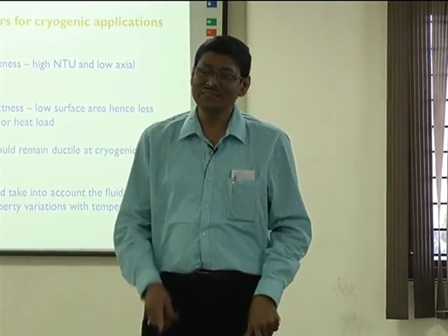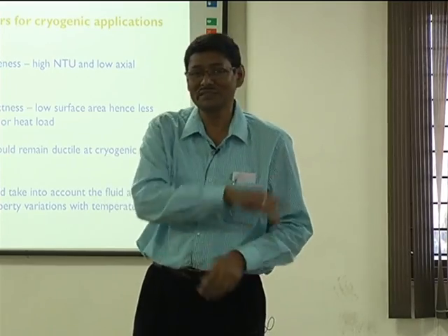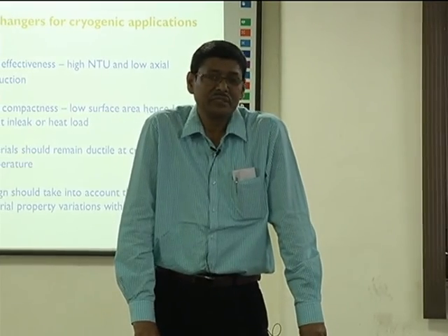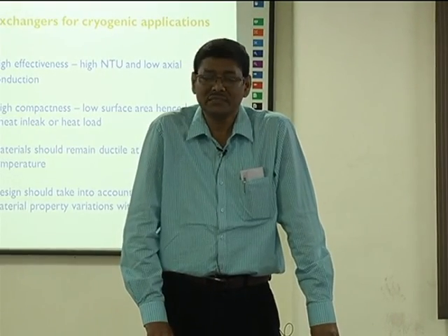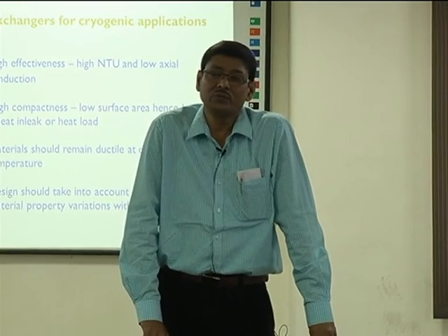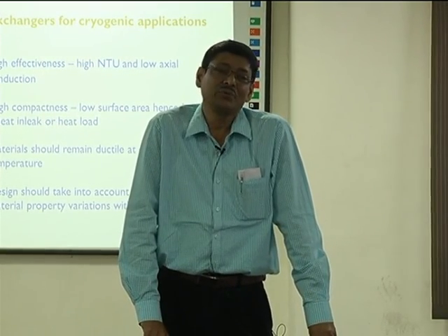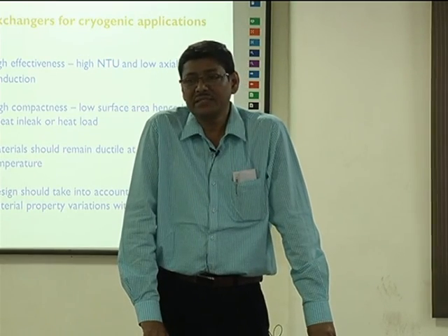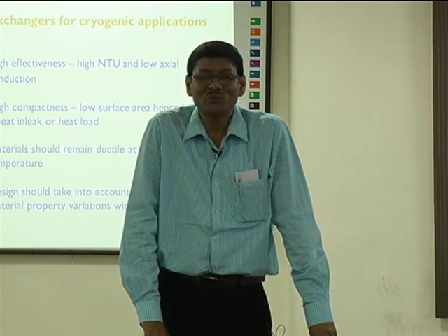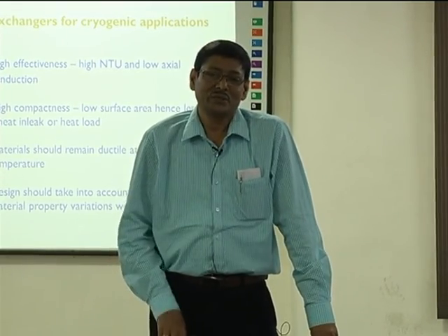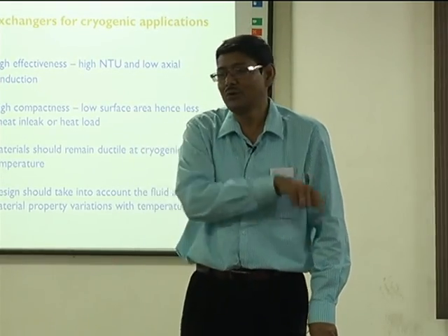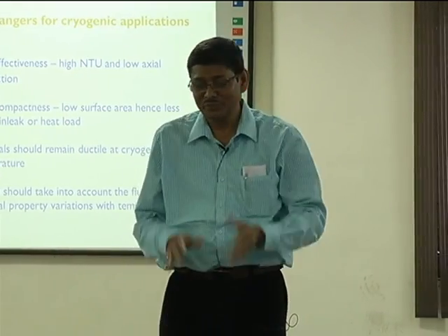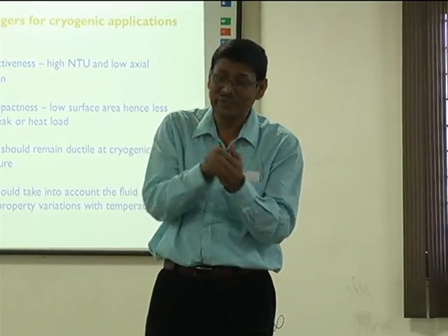To do that, the sensor has to be cooled to near absolute zero temperature, near absolute zero, not exactly zero. Absolute zero is not possible, but we try to cool it down as low as possible. Maybe 10 K, 4 K, whatever we can do, so that the noise created by the sensor itself becomes negligible, and whatever it picks up comes from the ground, or, if it is for a military purpose, from a distance, not from the chamber where it is located.